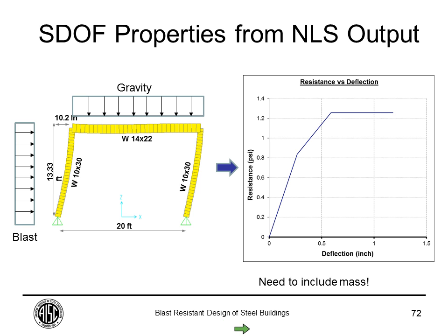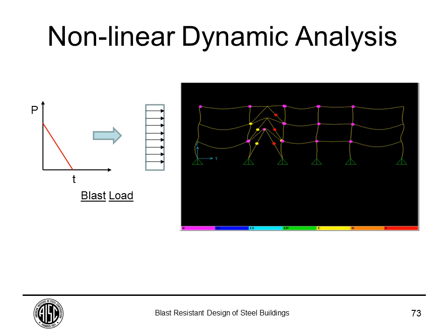Finally, in more sophisticated and higher fidelity cases, you can use structural dynamics software where you use hinges to account for nonlinearity, and you apply the load dynamically, and then you can see the full response of the building. In this case, we were looking at a brace frame, and we put a blast load on it and just pushed it to the very end, and we can see how the braces fail. So you see these hinges forming, and you can go a step further if you use LS-DYNA or finite element modeling, but generally this level should give you a pretty good result in terms of analyzing the full blast response of a frame building.